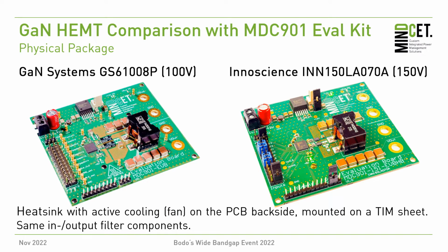Both of these devices are mounted on an evaluation board, as you can see here, together with the MDC 901 gate driver. Not shown here or not visible here is the active heatsink with a cooling fan on the bottom, which is connected to the PCB by means of a thermal interface sheet for a good thermal contact.